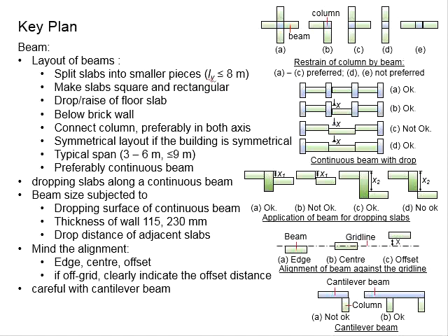Normally we will do one more analysis with a smaller size, see if the beam section can be reduced, and observe the amount of reinforcement bar required within the beam. If the beam fails, that means the size that you used previously will be more economical, or will be the right size for the member.